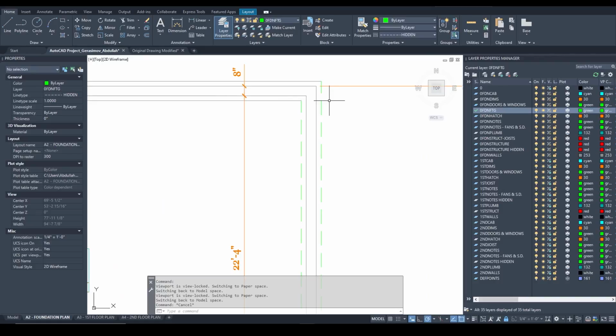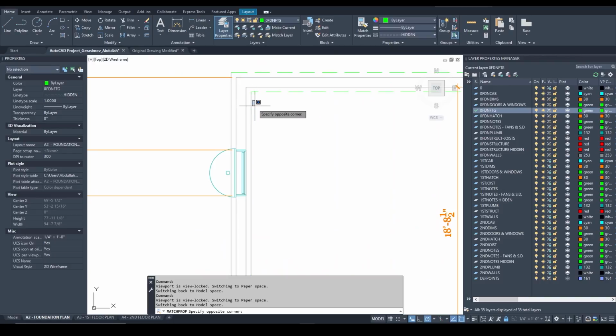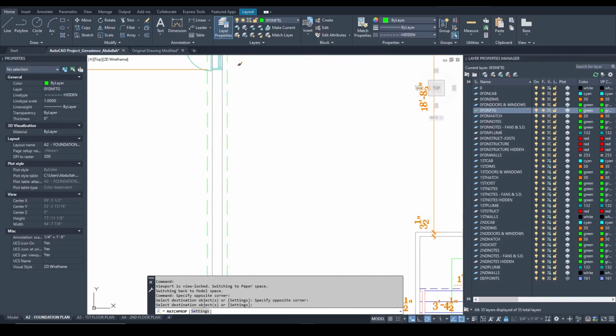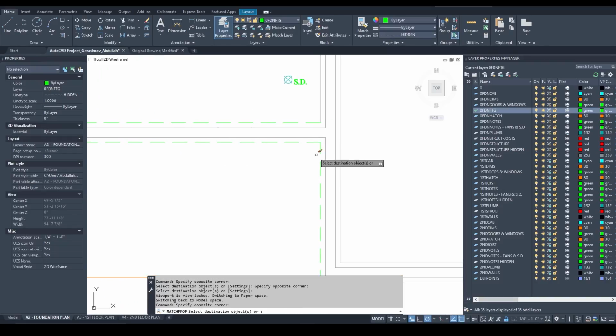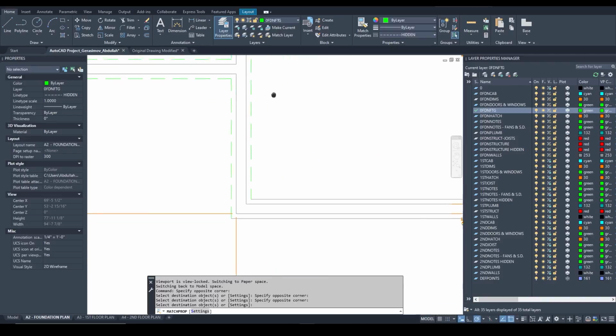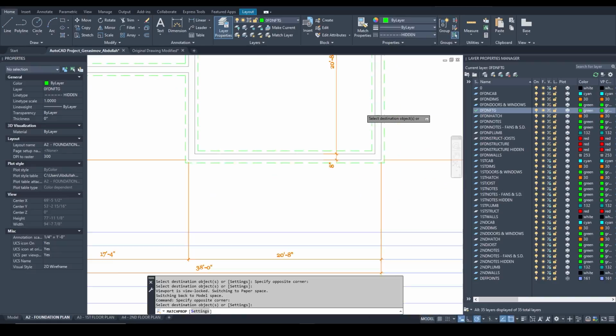Another way you can go about this, instead of manually selecting the layer, is to use a command that's already created called MA, match properties, selecting the line that you want any other line to be like, and then pressing on the lines that you want to change. In this case, you want to change all the 4-inch offset lines that we have just now created. We do not need to dimension them since they are hidden beneath the ground, and we really don't care right now for their exact location.